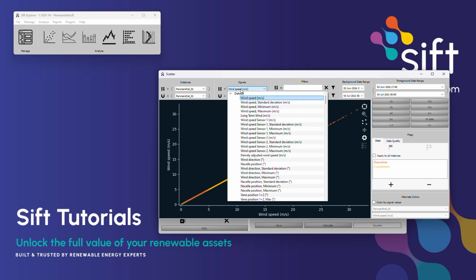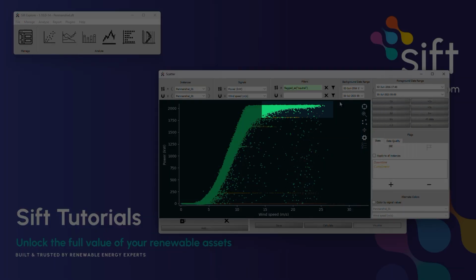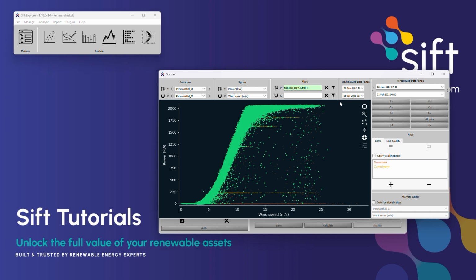In this analysis, we will compute turbine power curve efficiency in normal uncurtailed operation over time. We will create separate metrics of turbine efficiency at full load, where we expect rated power, and partial load, where the turbine is producing power but does not reach rated. Having two targeted metrics for the different parts of the power curve makes the output easier to interpret. Let's focus on partial load operation first.